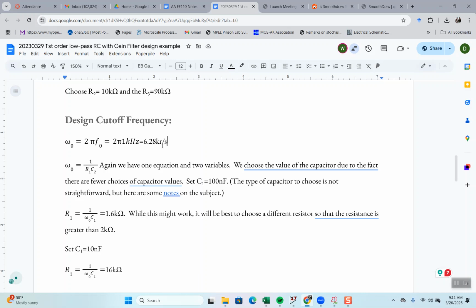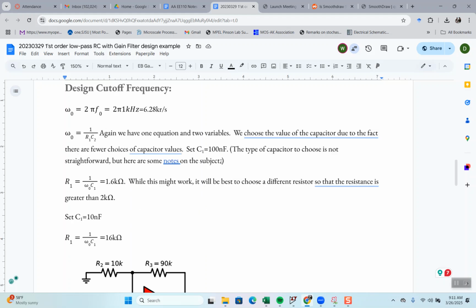The transfer functions, of course, are in radians, so that when you solve for RC, then it's just RNC. That 2 pi, that number 6.28, can add confusion. But yes, the analog wizard from Analog Devices, every data sheet gives their gain bandwidth. It's all in hertz, right? Bode plots from LTspice are in hertz. But anyway, so the thing is, what do we do?